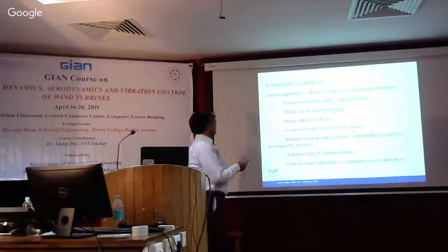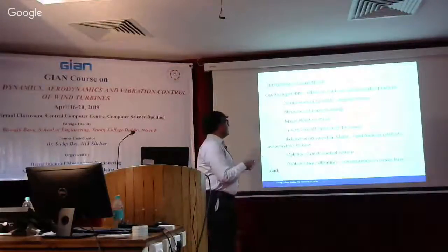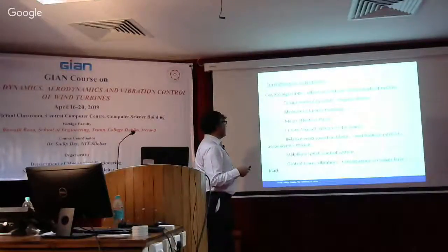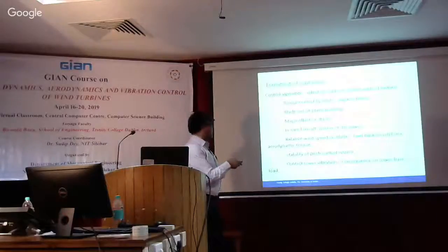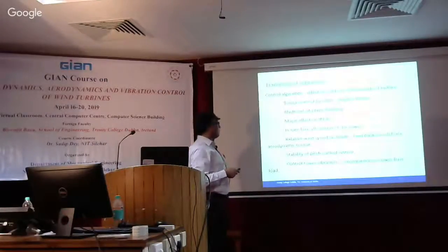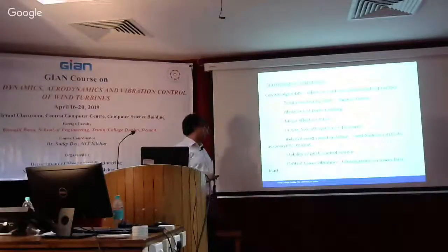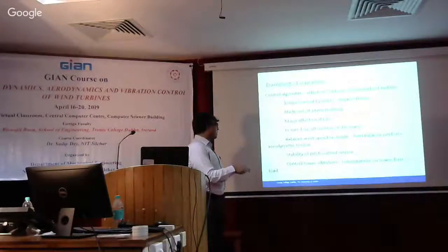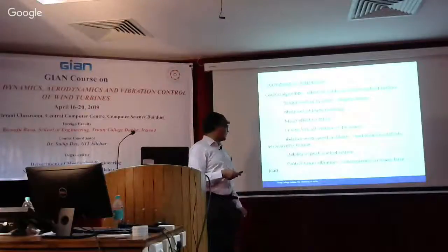So again, as I said, the pitch control can control the torque, control the thrust, and blade out-of-plane bending. It has a major impact on the thrust, which we'll see very soon, and also the forward motion of the tower. And the relative wind speed of the blade is changed, obviously. But the stability of pitch control is also very important. And people have successfully used pitch control for tower vibration control, since the damping of the tower is low.